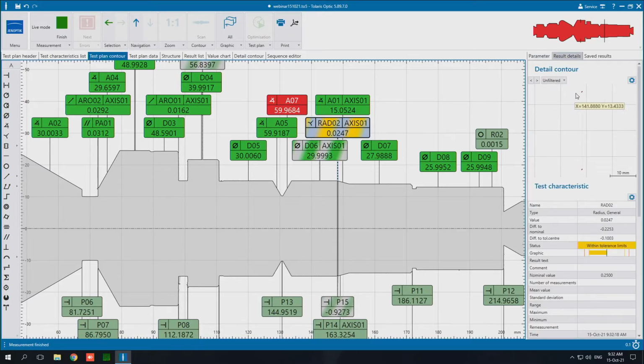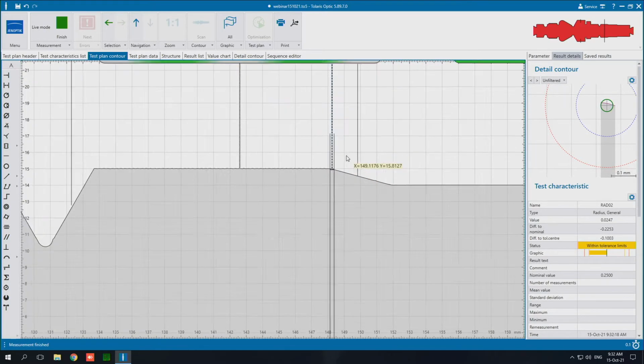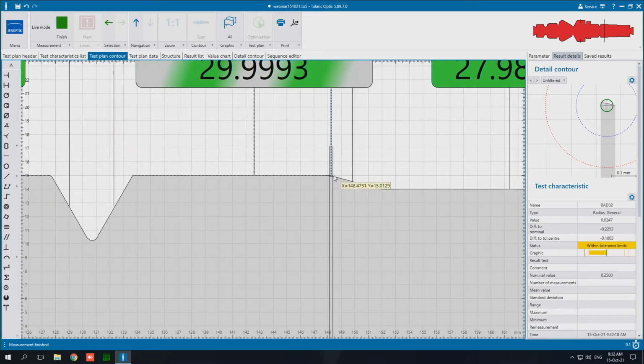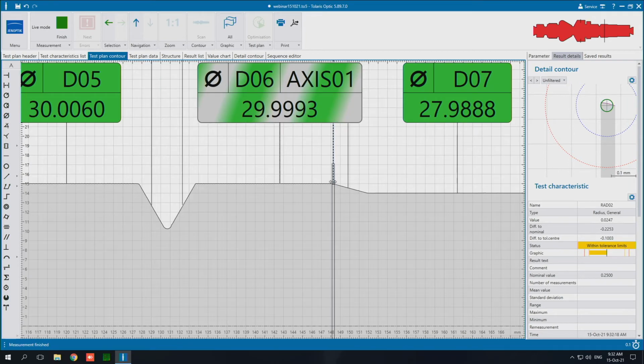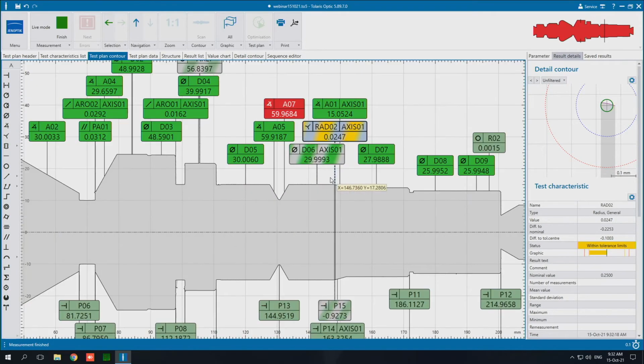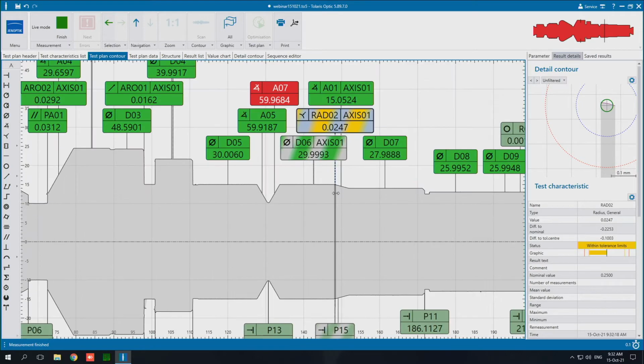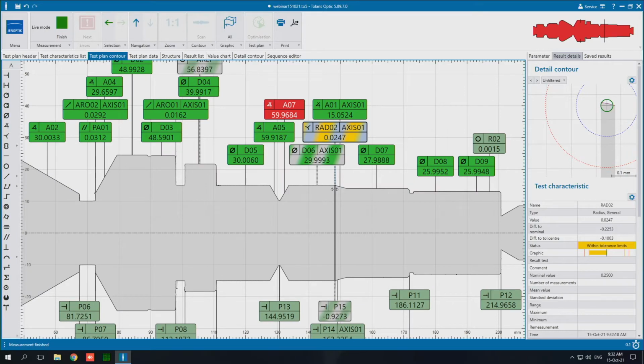You can see it's a lot smaller than that, but we're always going to find that radius because we've constrained it so effectively. So this can be done on any corner radius or any break edge that we're looking for, and that can be used in multiple ways to keep things constrained when they move around a lot and we still want to know what they are.